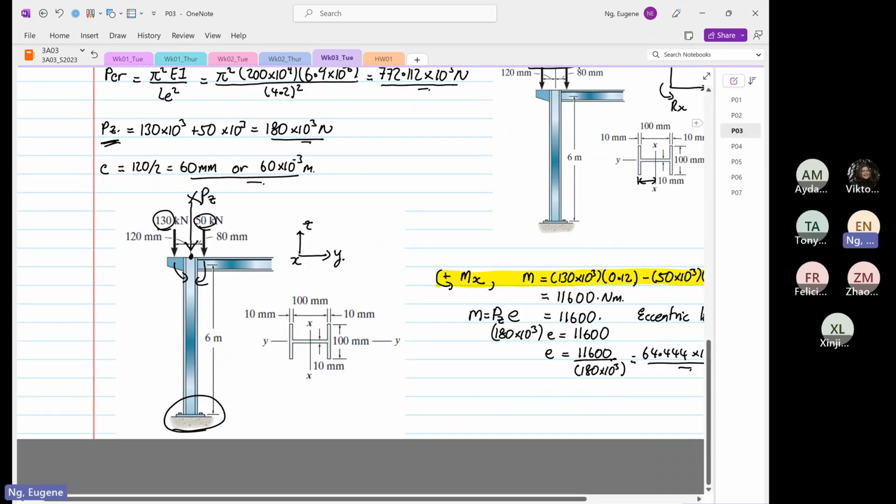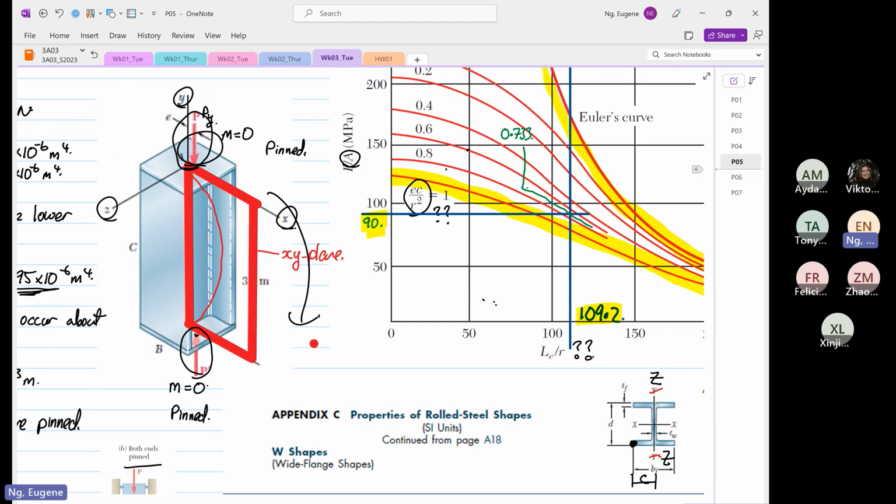It's different, yes or no? What we have on the other one is just a single point pin, so there's no resisting moment. To see what sort of holding system you have, you have to watch your moment. That's the way to see how the structure is fixed.